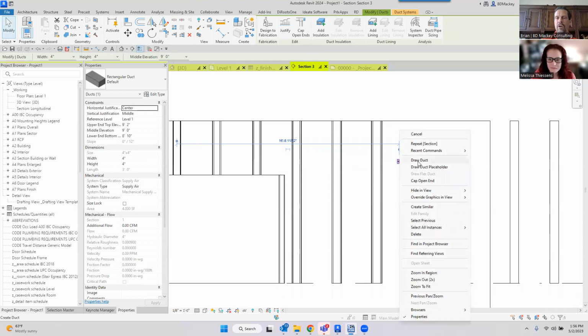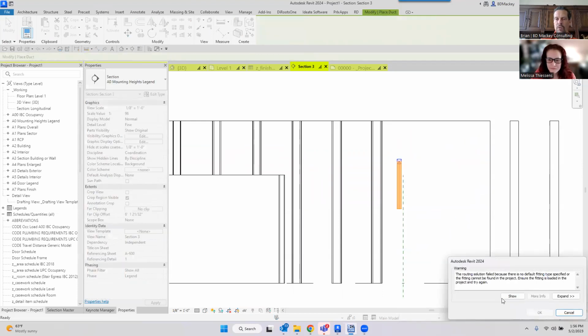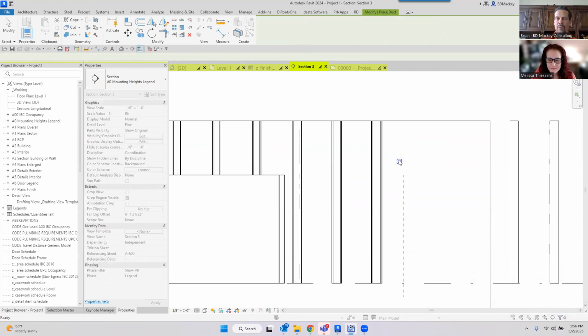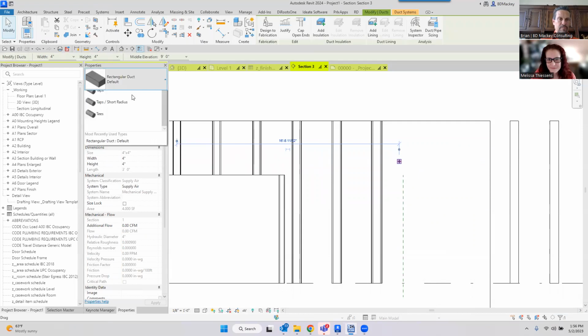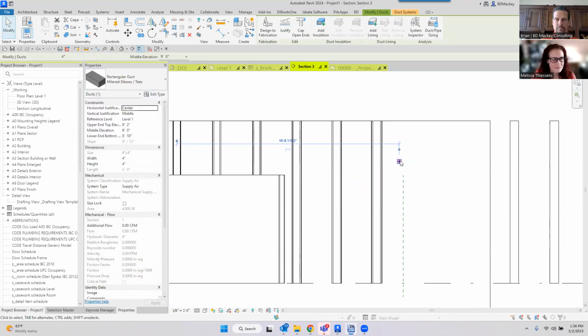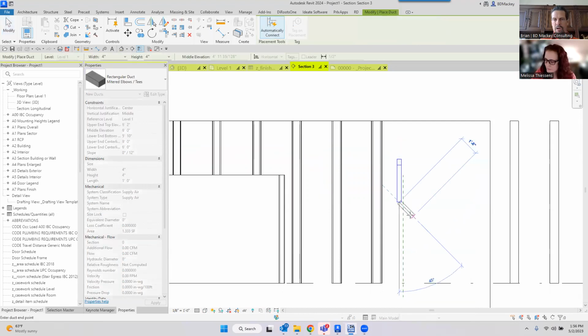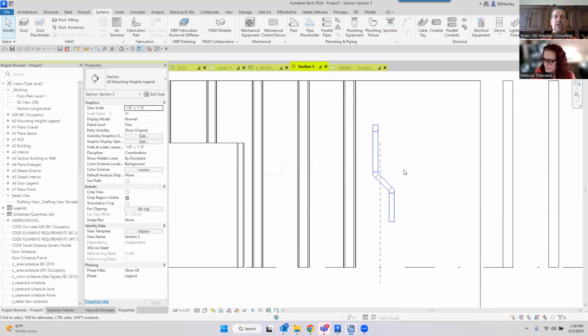So if I just right click on that grip, I can say draw a duct. And now I can be like, oh, I needed to come down. I told you I probably don't have elbows drawn in here. See what else do I have? See if I can change it to, there we go. Draw a duct. Come down here, come over here, go down this way. And then you're like, oh, but now I need to go the other direction. Switch to an elevation view, start drawing it in elevation view, etc.